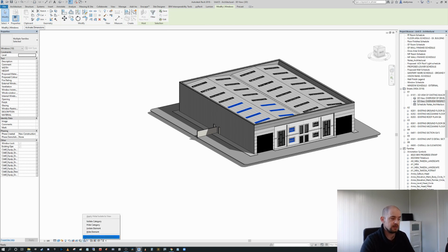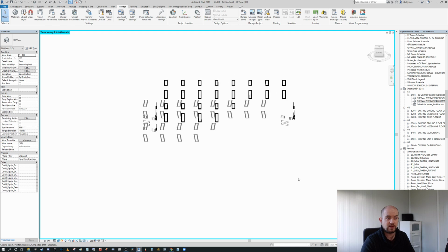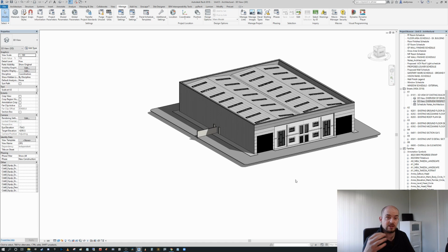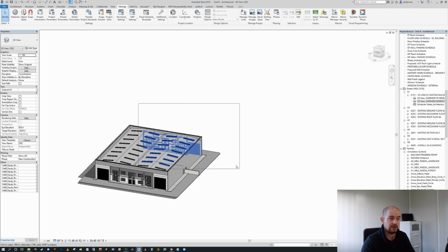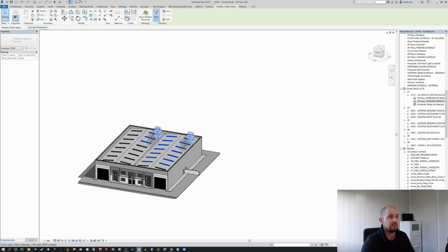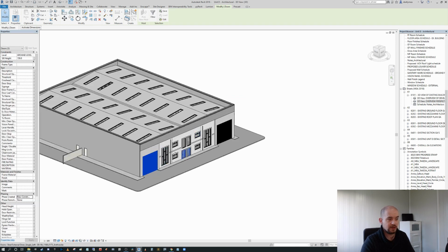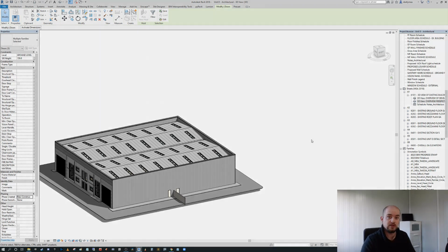When you combine this with the hide isolate category or the hide isolate elements, okay, it becomes a very, very quick way of controlling the overall selection and presentation of elements that you are selecting. Okay, so it's just to be cognizant that we can actually really efficiently make selections en masse by pressing the filter option when we get our contextual dialog box opening in the ribbon, checking none, and in this instance I'm going to pick doors, I'm going to press apply, and you'll see that we now have 3 doors in the selection. Okay, so that was number 3, how to make selections in Revit using filters.